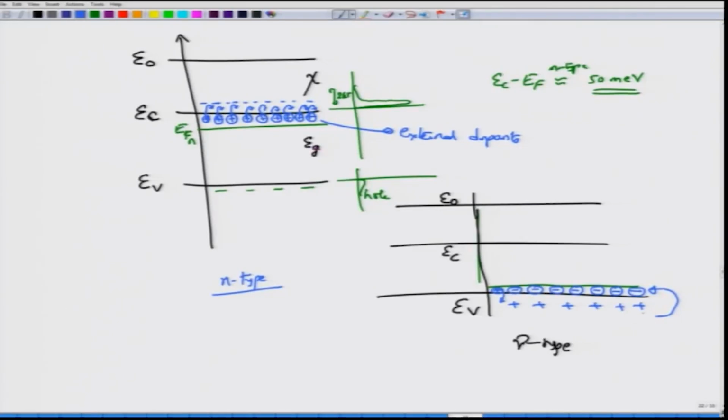When it just went up to this one, which we will call the Fermi level EFP, it left behind a positively charged hole here. So, that is how the holes were produced, but we do not really need to worry about that. What we see here is that once you have the material doped p-type, then the Fermi level moves very close to the valence band, and the valence band will now have excess holes here. Okay. So, if you look, the concentration will be quite high here and then drops off,